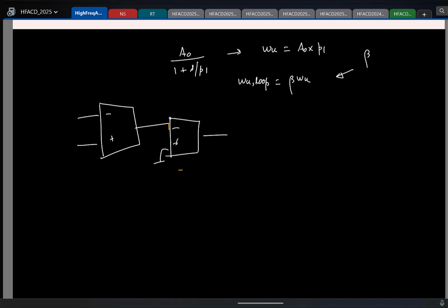So we actually do not know if this can be stable or not. Technically you should look at the closed loop poles and see if they are in the left half of the S plane. But the proxy way we took is the following. We sketch the Bode plot and look at the phase margin. And if the phase margin is sufficiently large, we say that it is stable.